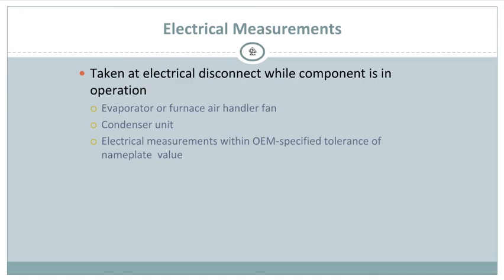So you're going to talk about the condenser unit, the amperage. Again, this is all going to be measured in amperage, 240s, 120s, whatever the amperage may be for that unit. Most of them are going to be 240 because they're big units. If you do window units, those will probably be a 120, or 110. But again, depending on the system you're using, the equipment, the size, that'll depend on the amperage.